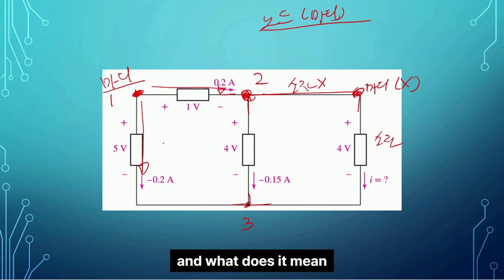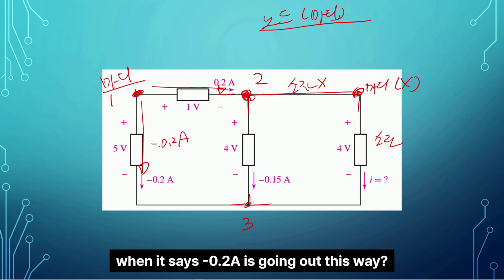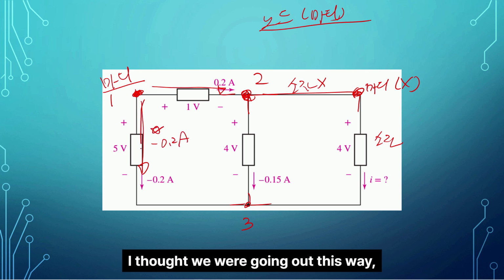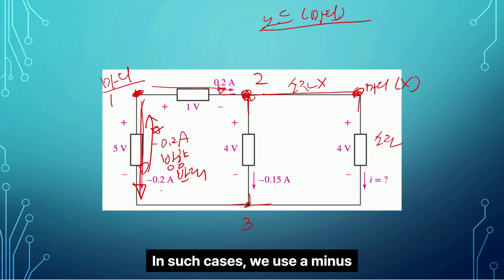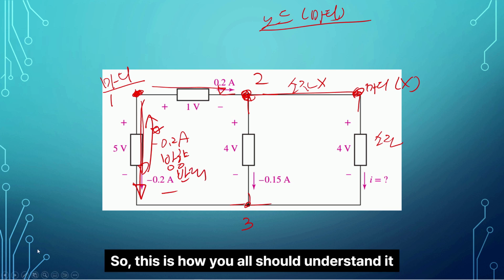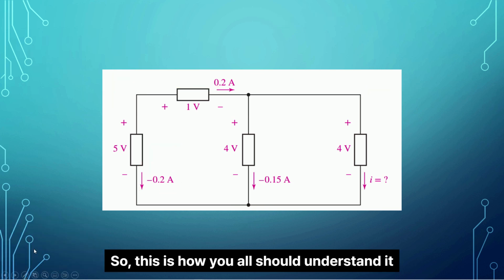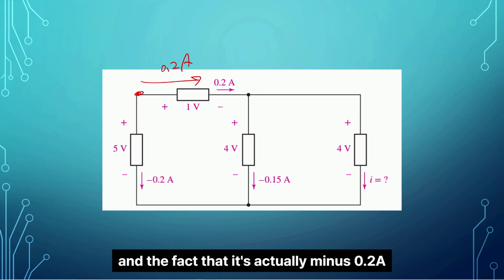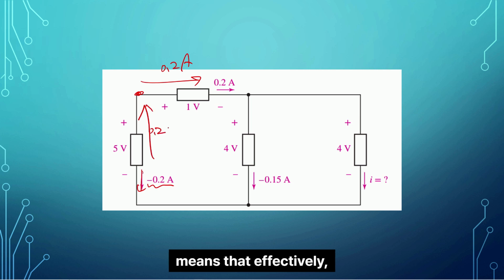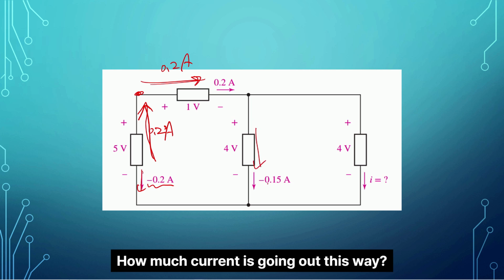And what does it mean? When it says 0.2A is going out this way, I thought it was going out this way, but in reality, the direction was the opposite. In such cases, we use a minus, so this is how you all should understand it. So, if you look at it from this perspective, 0.2A is going out this way. And the fact that it's actually minus 0.2A means that effectively 0.2A is coming in this way. How much current is going out this way?